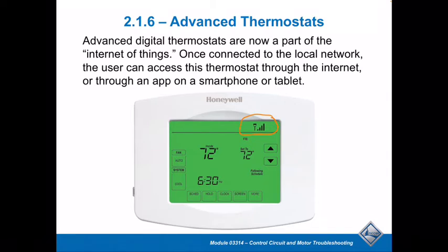In years past, we would have had to put an anti-short cycle timer on a compressor circuit so that we didn't short cycle the compressor. Nowadays, you can put in a 5-minute delay between cycles, so if somebody turns the thermostat down and then decides to turn right back up, or vice versa, you're not going to allow the system to turn on and off and on and off. It's a much better application. Good temperature control, a lot of different things.